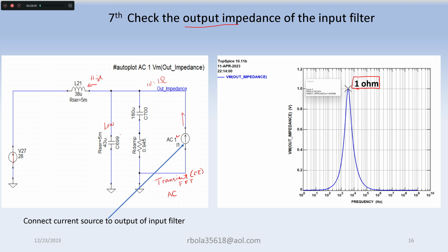And since this capacitor is much bigger than this one, or at least 4 times to 10 times, it is the dominant impedance. So basically this should be kind of like a short by 1 over ωC. So as C goes up, the impedance goes down. And basically you can think of this as a short.